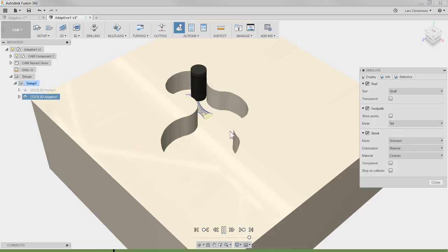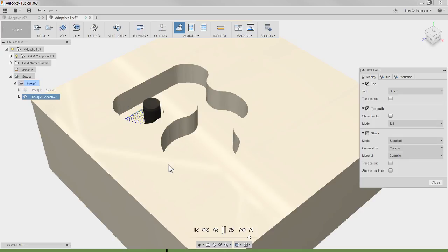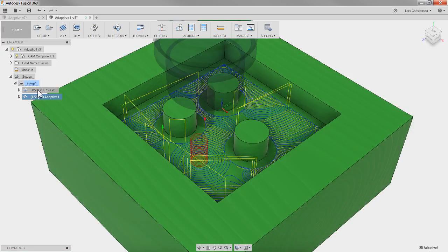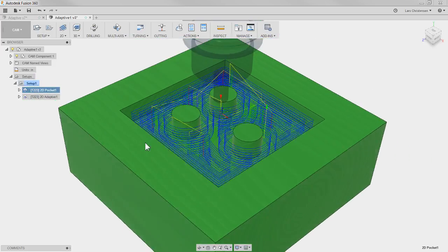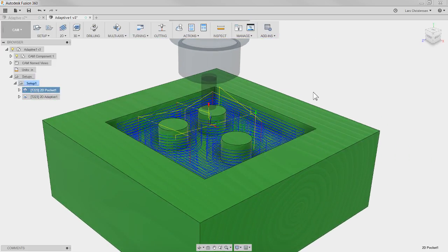Now you want to have coolant shooting all the chips out, because you are going to create a lot of chips. But from a wear standpoint on your machine, think about the way I used to do a lot of this milling, and what we did when we started out: we did that 100 thousandths. The bottom of your end mill, that corner between the bottom and the side, is a sharp edge. That's going to break down first.